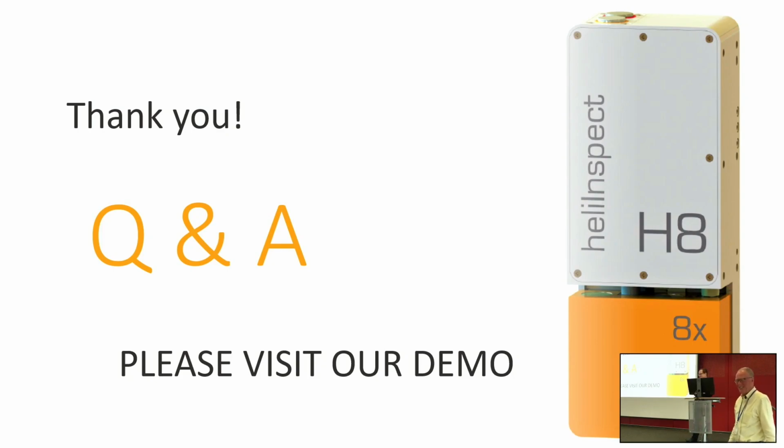Thank you. So very briefly, my experience of white light interferometry is that on steep surfaces you miss large chunks. Effectively, a lot of the machines interpolate the data. And I think some of the parameters are more affected by that than others. It biases some of the parameters.